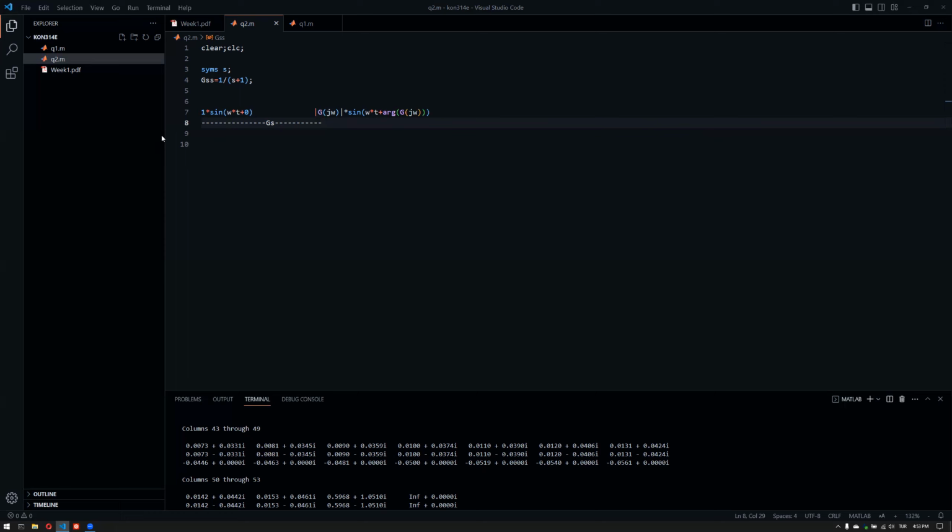We can use the symbolic toolbox because this is basically a way of manipulating things here. And we can plug in s equals j omega, or 1i times omega in terms of MATLAB. This transitioning from the s domain into the omega domain, or frequency domain, is nothing arbitrary. This is basically the transitioning from Laplace transform into Fourier transform, which is quite interesting if you ask me, because Laplace transform is something that we use in control system theory, but the Fourier transform is more of a